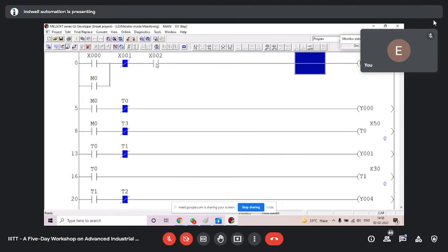Now you will ask the operator or electrician, what is this X2? He will check and will tell you, okay, it is a sensor. And then you will reach that sensor and check whether it is out of order or its position has moved. Now I am going to fix the position. You see, look at the screen. See, the sensor is on now.